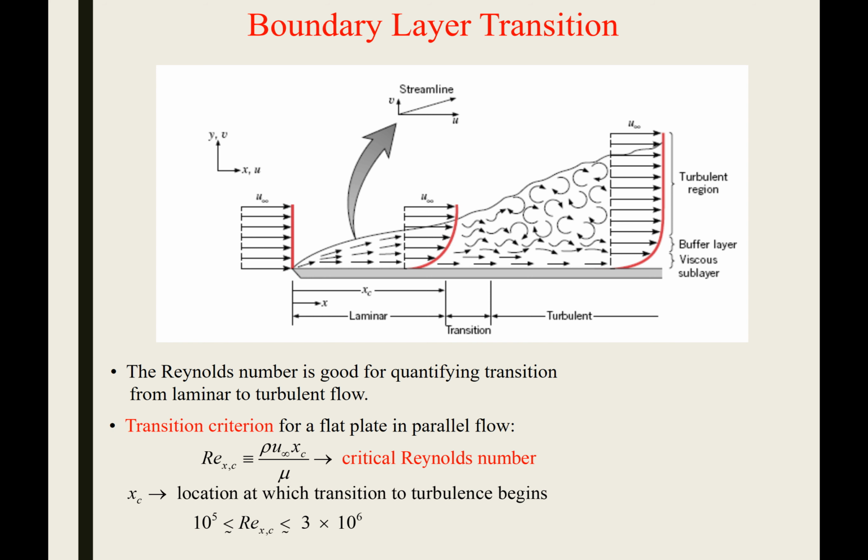Any questions there? So just kind of a fundamental thing to keep in mind. This is just a totally different geometry. So our Reynolds number is defined differently, and the point at which we transition from laminar to turbulent is different. And there's actually a physical transition. So let's say that the critical Reynolds number happened halfway through.